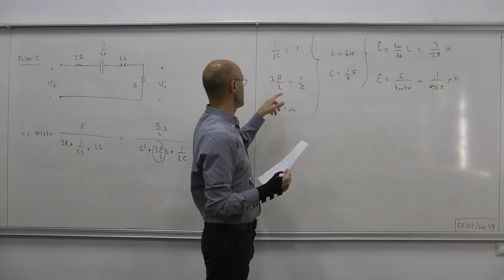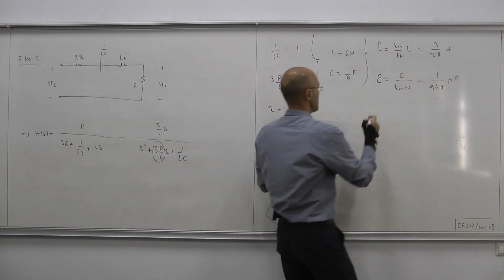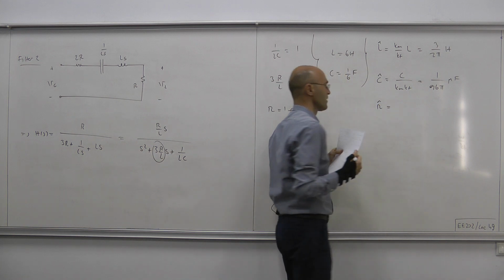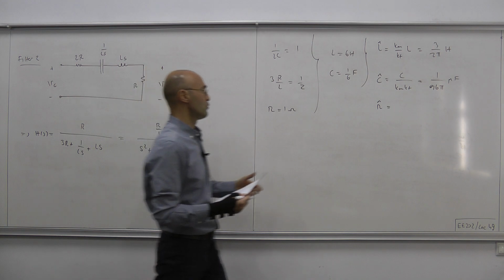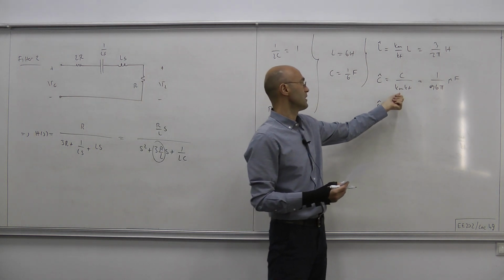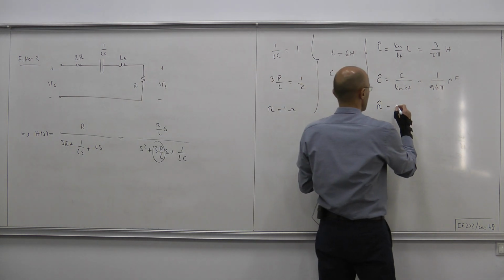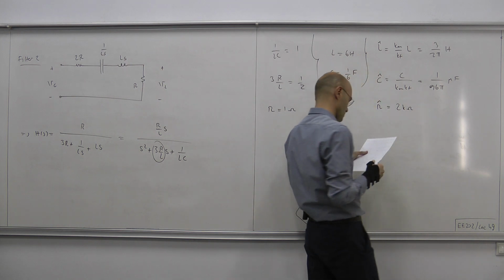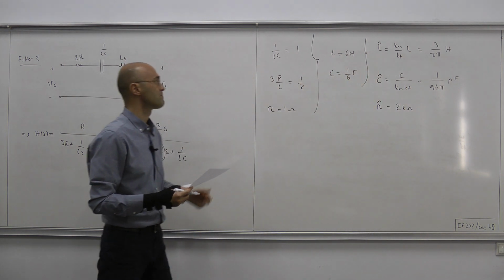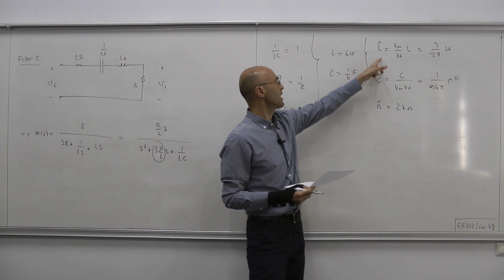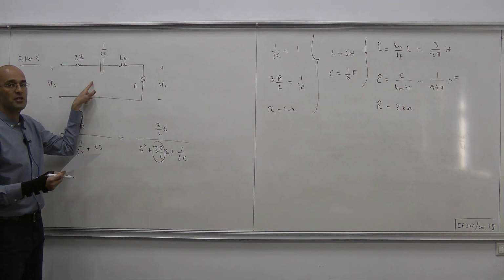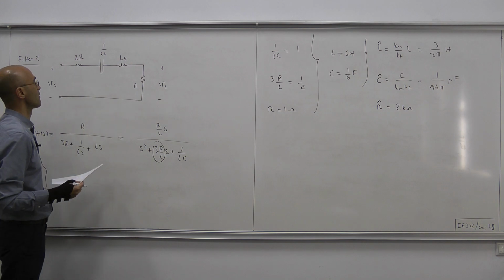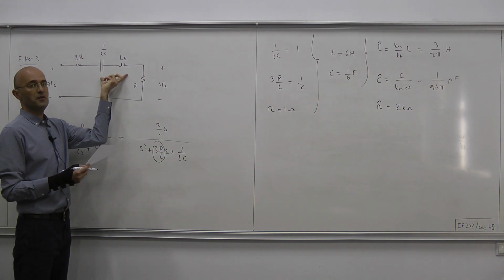And finally, our desired resistance, through which we computed the magnitude scaling factor to be 2000, equals 2 kilo ohms. So that's another possibility. Pick those L hat, C hat, R hat values, and set the topology of your LC filter as this series connection.